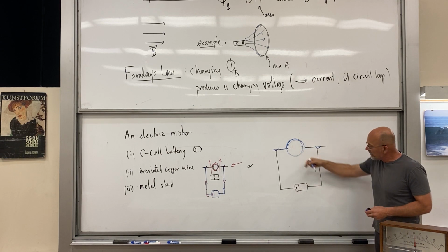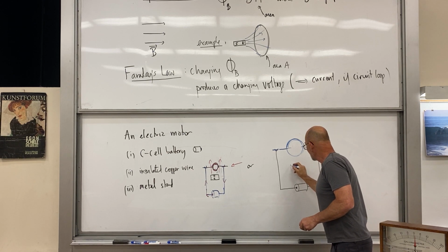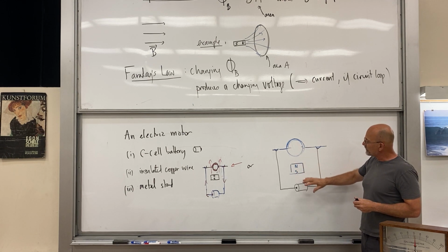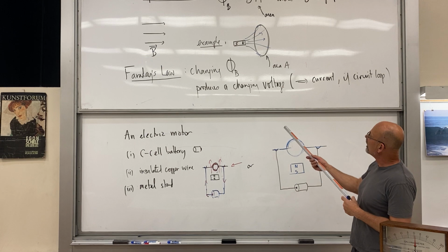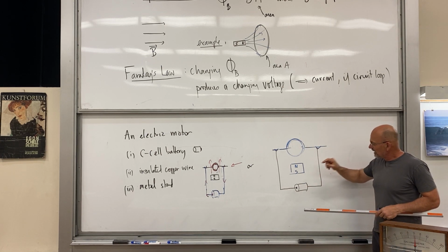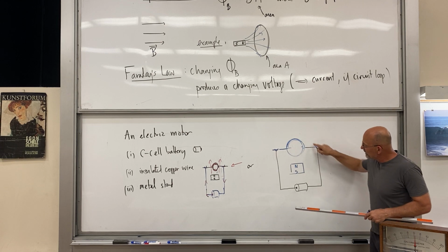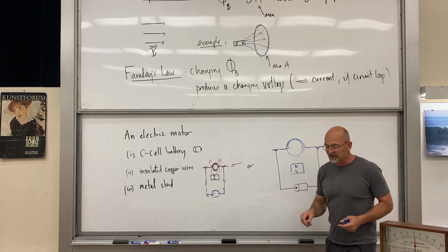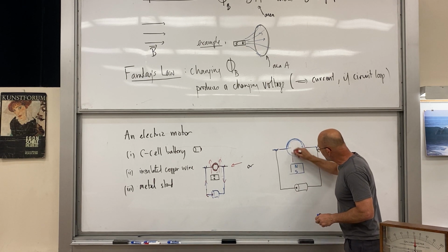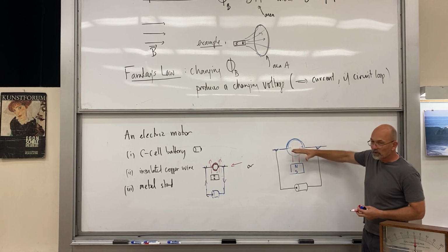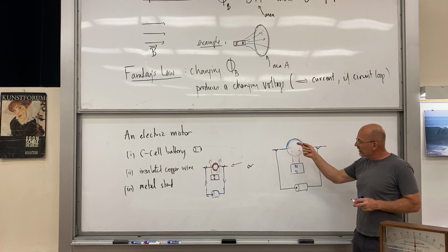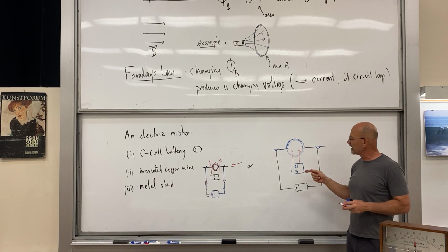So yeah, this thing was rotating if there was a magnet here. I'll just indicate this with the north and the south. It was spinning in the presence of the magnet because of that law that I've erased, in which if there's a current through this thing, then the B field is acting on the current and producing a force, and it produces a torque. So one thing you can do with this little machine is carefully hold it with your finger, and you'll feel that little bit of torque in the presence of the battery.